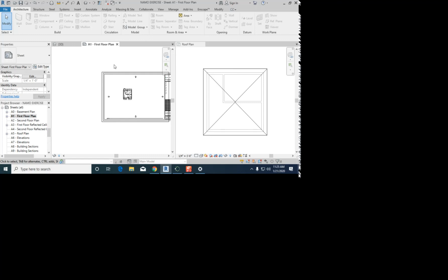Awesome. So the next question was, which templates do we use in this class? Architectural, residential. Which one isn't predefined in that new menu screen? Residential. Yep, you have to go looking for residential, okay? When you start dimensioning, what should your constraints be set to? So by default, when you start dimensioning, it goes to the center of your wall.